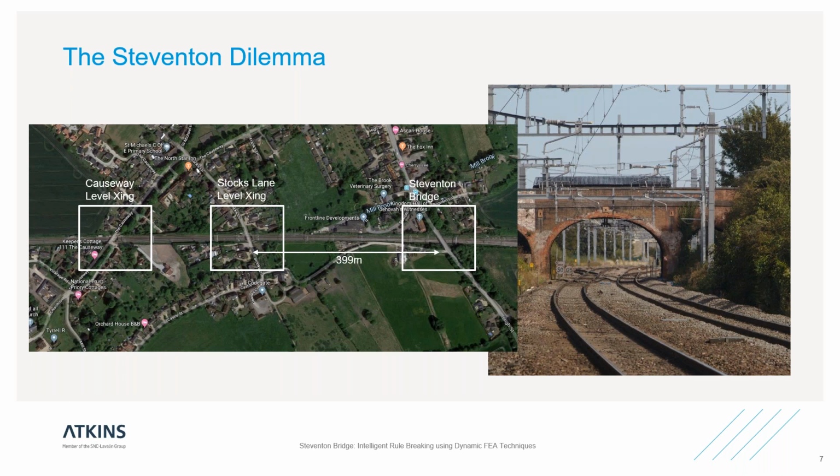Now, none of this mattered much until in 2009, DfT and Network Rail decided to electrify Great Western. And Network Rail did some early work on the route, and that clearly identified that the high wire needed at the level crossing and the low wire needed at the bridge were fundamentally incompatible. The gradient between the two would limit electric train speeds to 60 miles an hour on a route which is otherwise 125 miles an hour. Now, this would have added around about 1.5 minutes to the timetable on a project that was supposed to be speeding trains up.